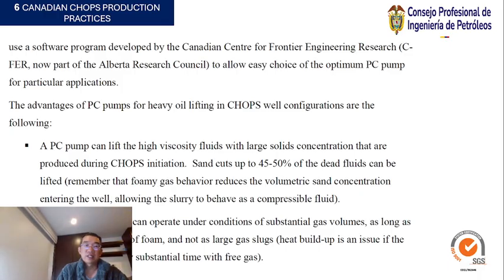The advantages of PC pumps for heavy oil lifting in CHOPS wells are the following: a PC pump can lift high viscosity fluid with large solid concentrations, as are produced during CHOPS production.